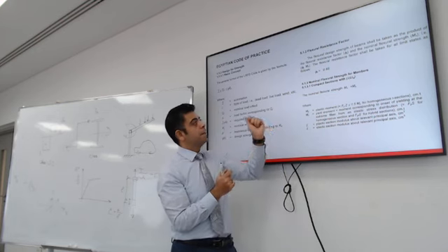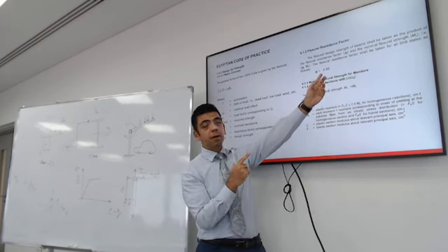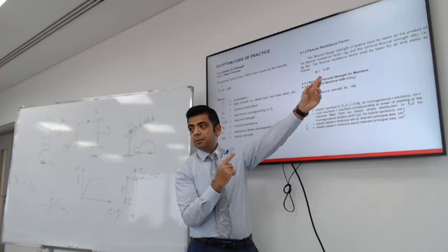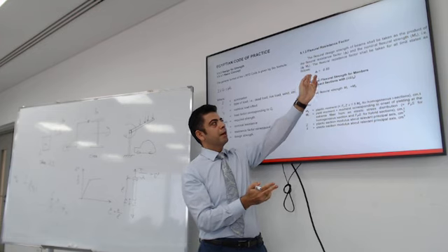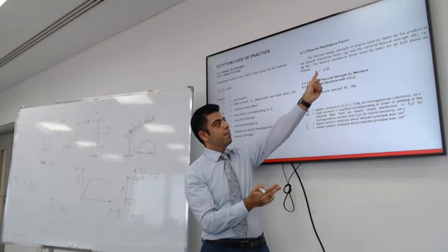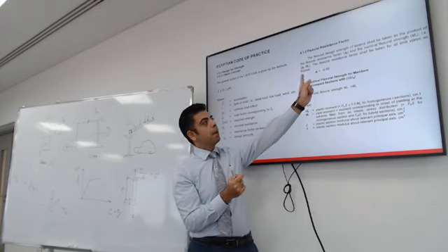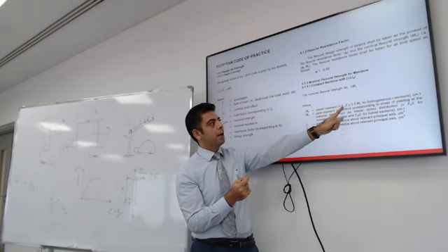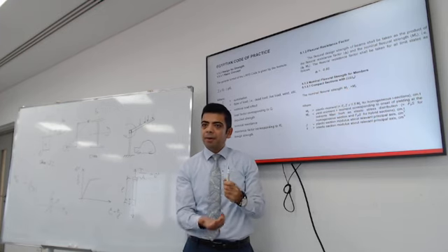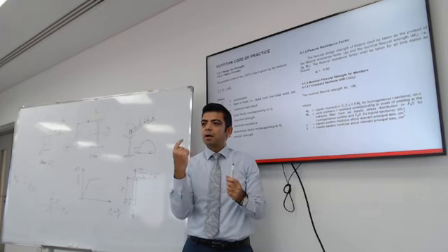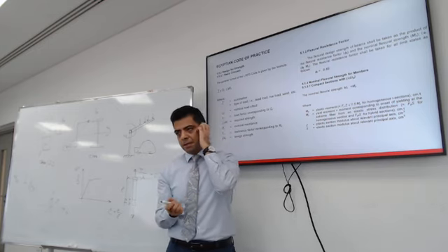The factor of safety in the Eurocode is gamma, gamma M0 and gamma M1. In the Egyptian code, it's phi-b for bending, and it's multiplied by the capacity. In the Eurocode, it's divided. So it's bigger than 1 in the Eurocode, less than 1 in the Egyptian code. That's pretty much it.